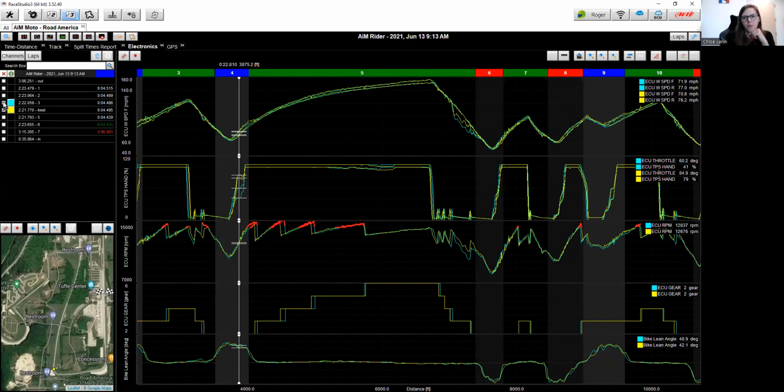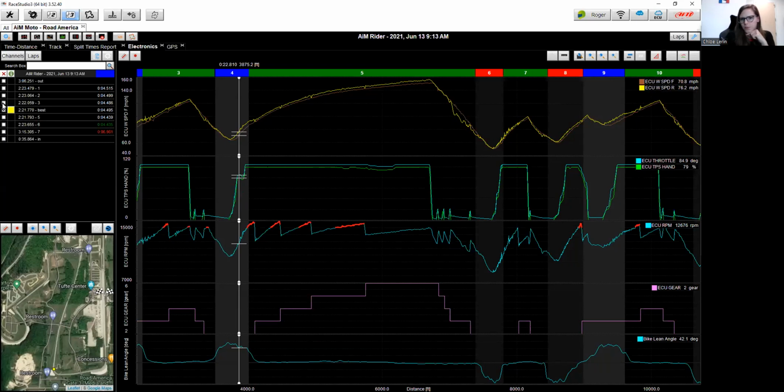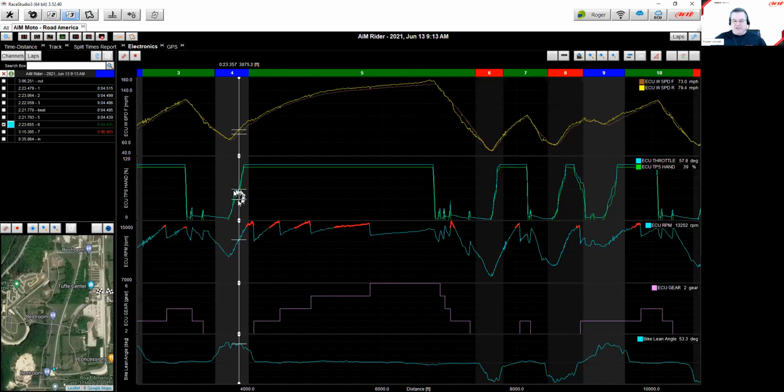Look how the rear wheel speed is increasing. He's probably sliding. Yeah, could be spinning the tire a little bit at that point, right? Yep. And I would look at multiple laps, and it's a consistent problem. Okay, now we take the next step. Why is this happening? It wasn't just that one lap. Yeah, and he's at full lean, so he's most likely spinning the tire.